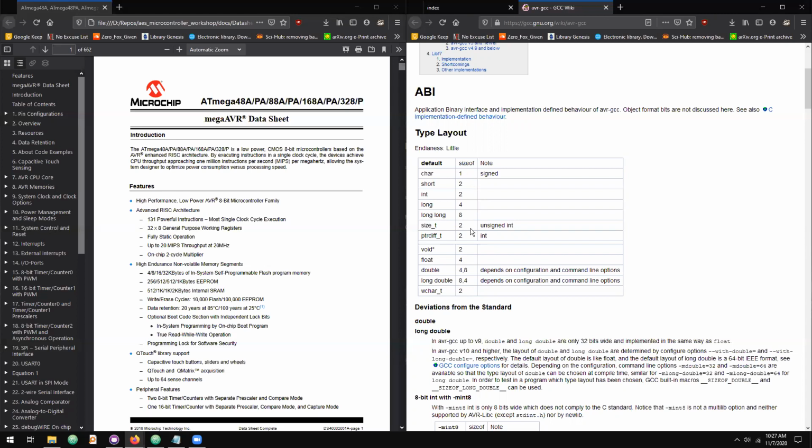But they do apply for AVR GCC. So we can count on a character primitive type being 1 byte, and so on. So apparently ints are actually 2 bytes rather than 4 on this kind of processor.